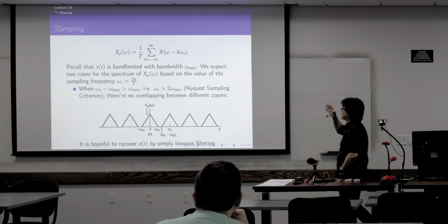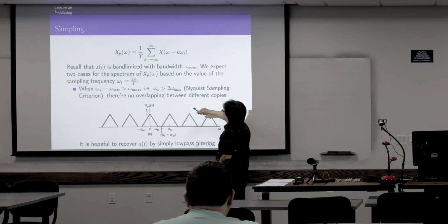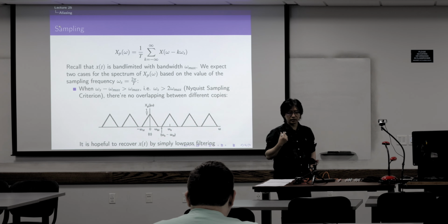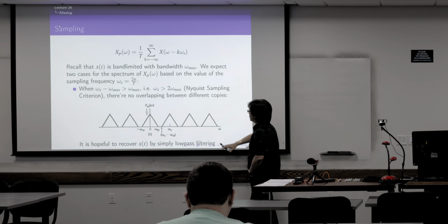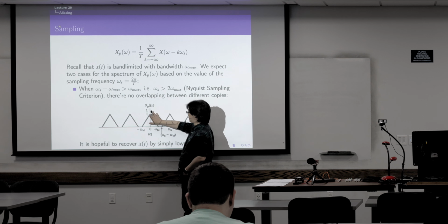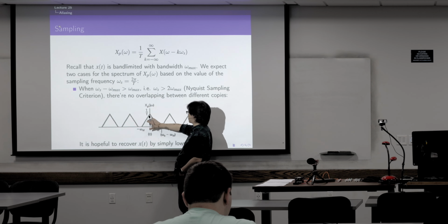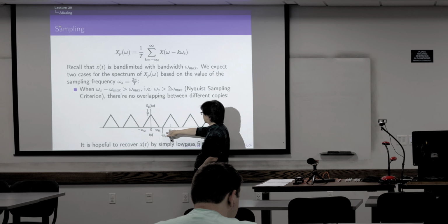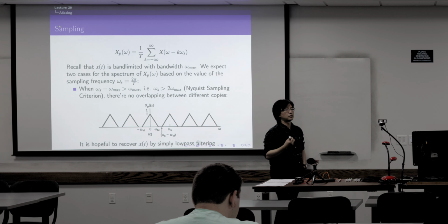So this is the impulse sampling, right? On the top, that is basically the frequency representation of the impulse sampled signal. So let's say this is our original signal. We need to reduce it by Ts times, and then make it periodic. The period of the signal is omega s, or fs in hertz. Okay, so this is our sampled signal.